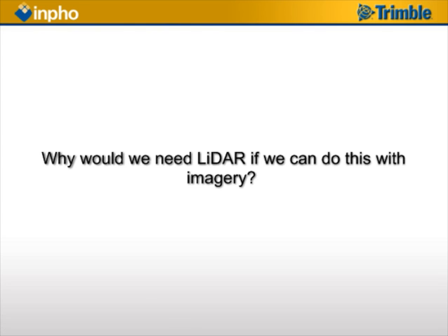One question is why would we need LiDAR if we can do this with imagery? Quite a provoking question, I guess. Okay. Well, in fact, what I was saying is that the matching might be an alternative to LiDAR. Of course, we have extremely good point clouds that we can extract from images. However, look, for example, at forest regions. In a forest region, using images for DSM extraction, you will never get the true ground. There's no way to penetrate through the forest to the true ground.